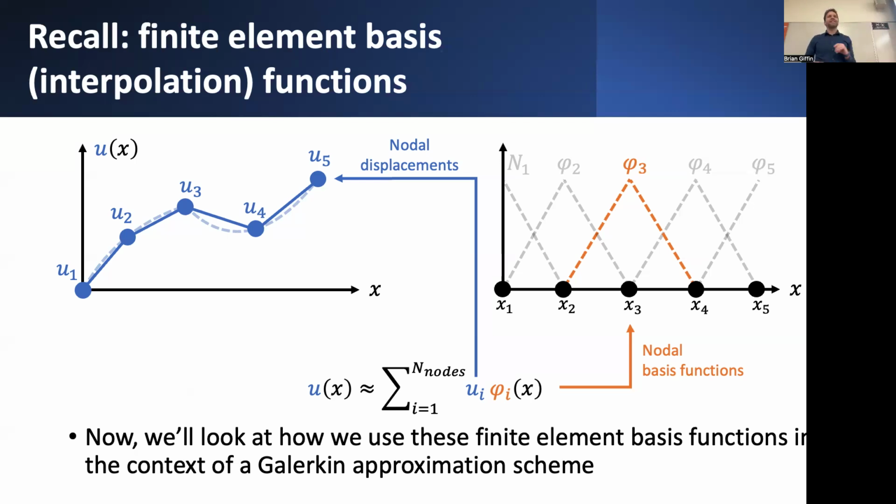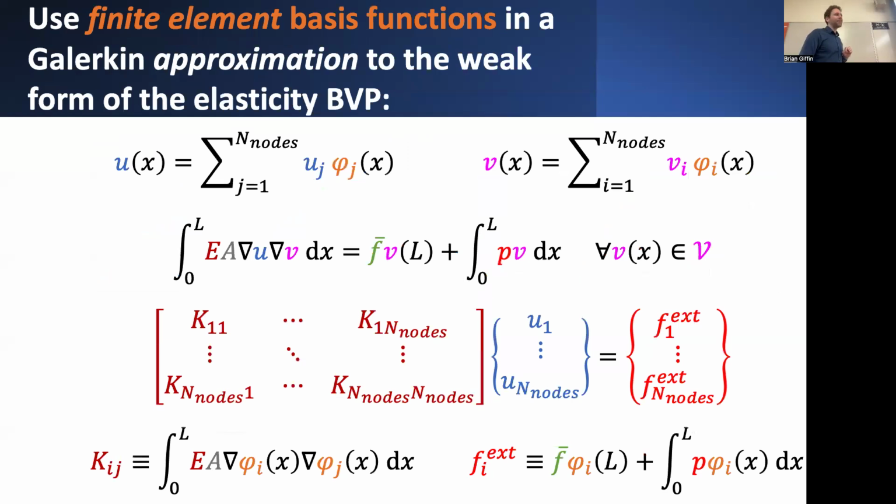And we came up with these interpolated representations of these discretely represented displacement fields, or solutions to these candidate boundary value problems. And we could take this particular choice of basis functions and this particular discrete representation of a solution field, and we could plug it in directly to our weak formulation of the elasticity boundary value problem.